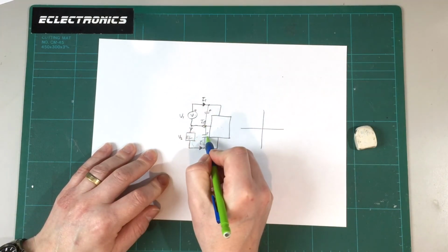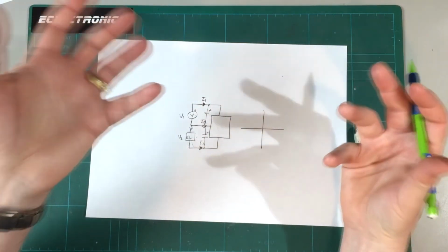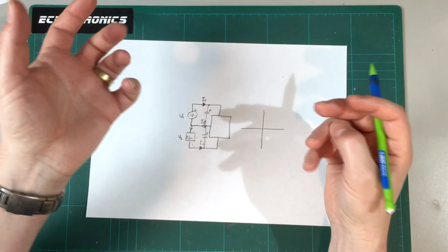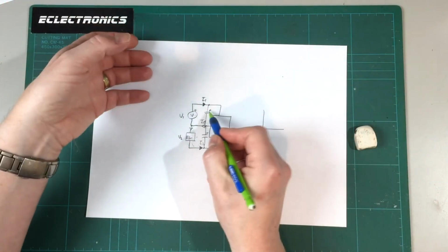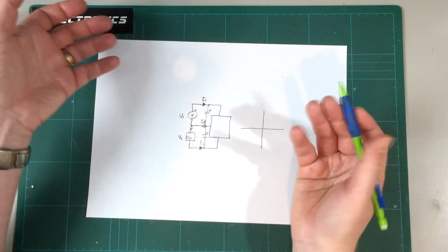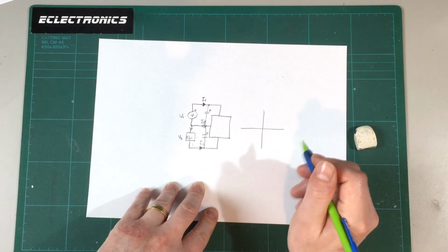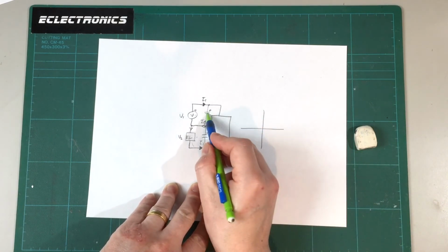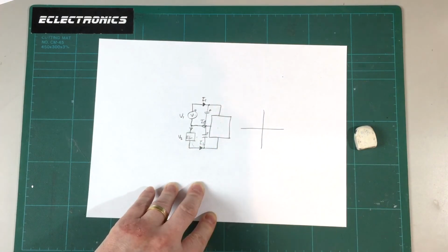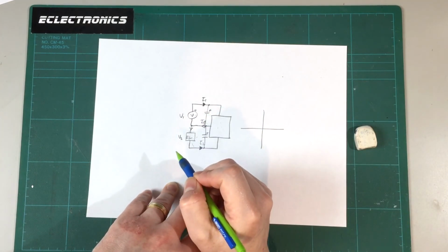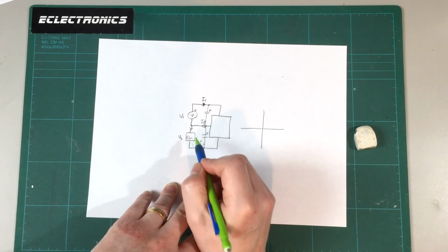So we may need to add some capacitors on there, but obviously with standard capacitors they're not like batteries in the sense that they take a while to charge, they don't hold a lot of energy, they're purely there to remove the ripple. They don't pass any DC current because they're capacitors, so I think they're not going to affect our transfer function measurement at all. So I think that's okay to do, and indeed there will be capacitors on board this circuit anyway already for this purpose, so I don't think there's any harm in adding those on there. But yeah, I think this is going to be very interesting to try.